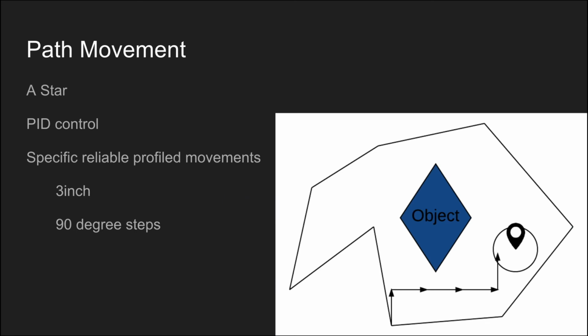Using data from the target locator and some calculations, we could tell which points were walkable and therefore could be added to the movement lists. With this information, we could use A*, a heuristic of Dijkstra's algorithm, to determine where to go. This algorithm gave us sets of points 3 inches apart that our rover could use to get to its destination while avoiding obstacles and staying inside the map.